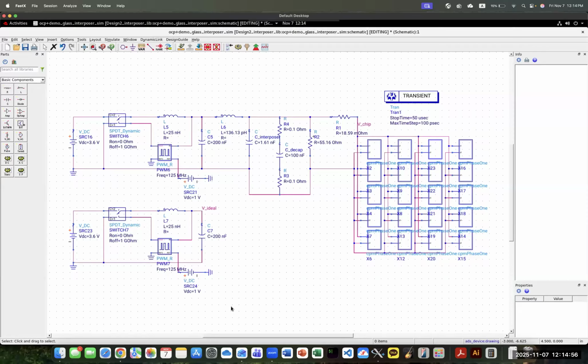And on the chiplet side, we need the CPM, which is the chip power model, that includes the PDN, PDN parasitics, and current waveform. And we also need, most importantly, the package parasitics, in S-parameter format or other formats.